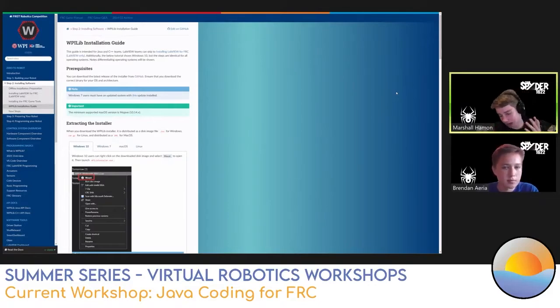That happens a lot of the time. There's also the issue where you're connected to the robot and some of your vendor libraries require online installation. For example, CTRE has online and offline libraries that you can access. Online libraries are where you tell WPILib the URL to pull the code from, and then it pulls the code from that URL. However, if you have a wireless connection to the robot and a wireless connection to the internet, you can only choose one at a time. So you have to build your code individually and pull it from the internet, and then compile it and push that out to the robot. You can encounter that frequently.